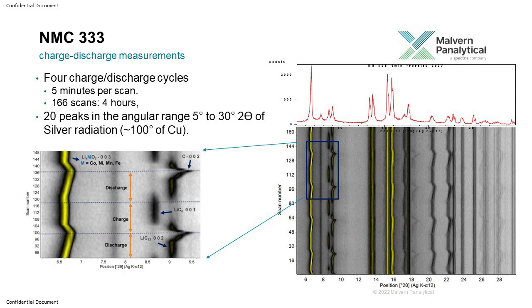Usually in the design, what they do is grading. So the nickel content is changing from the center to the surface of the particle. Instead of having the whole particle with homogeneous 80% nickel content, they will do the grading. As you come to the surface, the nickel content becomes lower and lower. And because at the surface the nickel content is lower, the particle gets more stabilized. And then there is some designing aspect of how you produce these graded kinds of particles.